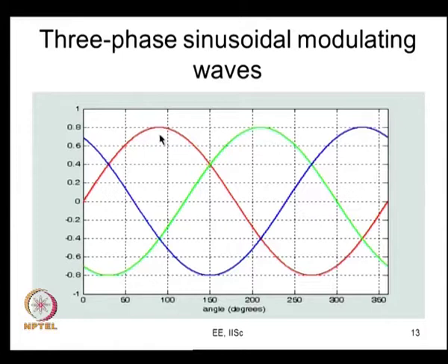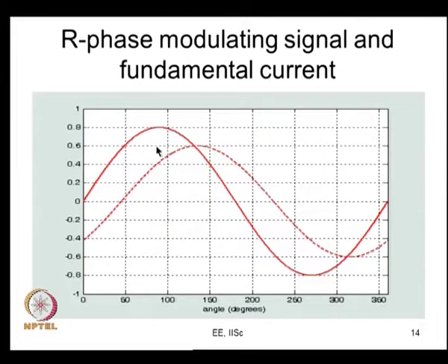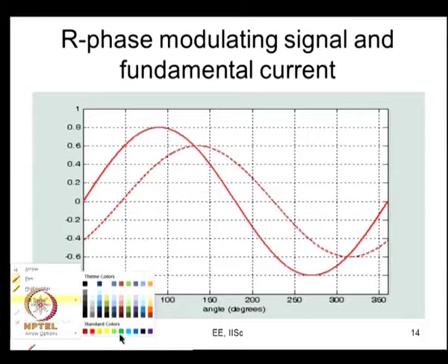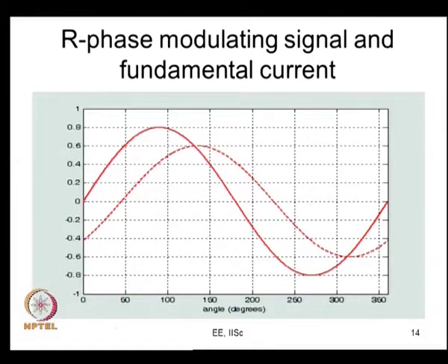Depending on the load impedance, there will be a corresponding fundamental current. Let us say this is the load current. There is a certain amount of current, and we saw that there is switching energy lost. Now, what is our simplifying assumption? The loss is proportional to the current that is being switched. If the current being switched is 0, the loss is also 0.